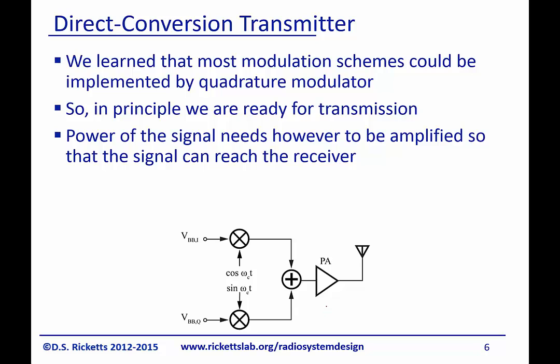And what we do is we introduce what's called a power amplifier. And the reason why we call it a power amplifier is that the metric that's used most often is total output power, also efficiency, and then also important in that is its linearity. And unlike small signal amplifiers, power amplifiers tend to trade off linearity and gain in order to get higher power, higher efficiency. So it's not that they're necessarily totally different from a regular amplifier. It's just that their designs are focused on different metrics than other amplifiers.